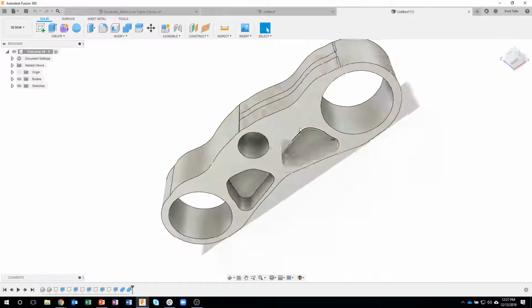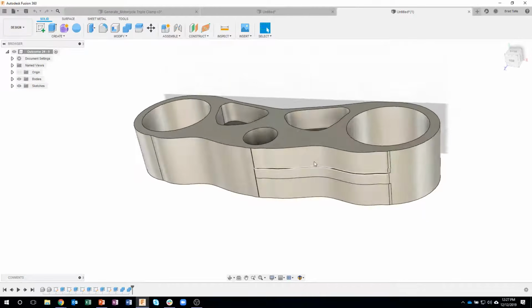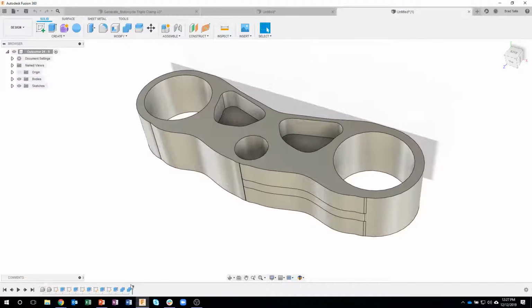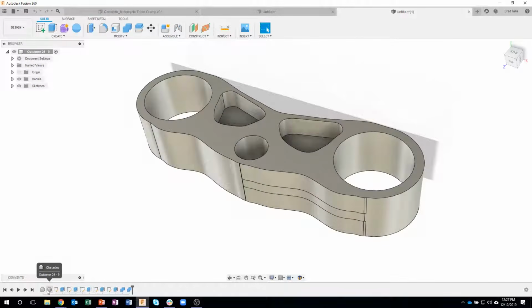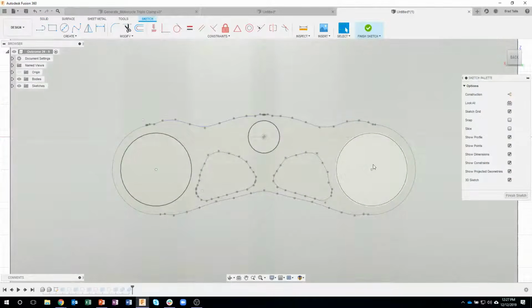So as I'm taking a look at this, notice this is an actual model. And we can even see, for example, where the layers were created. But take a look at the timeline. Here's our preserves. Here's our obstacles. So it actually brought those across for us. Okay. Then there's a sketch. And if I edit this sketch, you can actually see the spline that was created to create that particular shape. So it did all of this for me automatically.